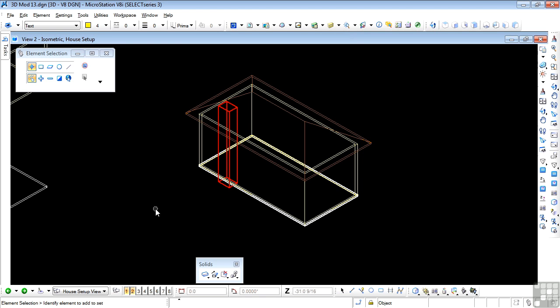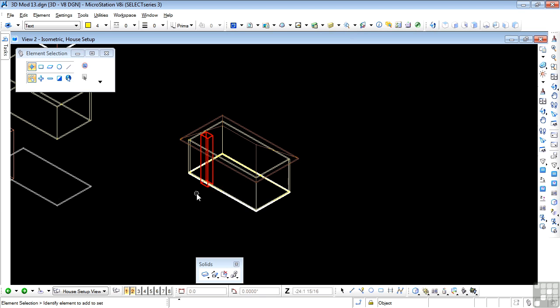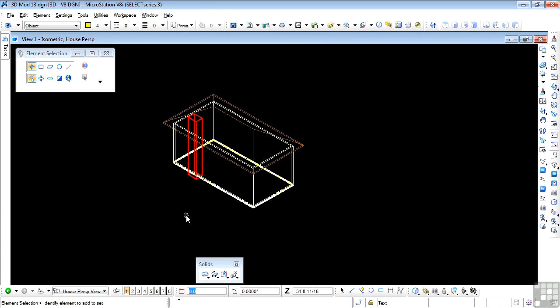Now that you have your house in place, we need to start looking at applying the camera. I'm going to change my model here to the same thing, but without the 4 individual items being displayed. Right now I'm in isometric. The camera is very simple to operate. Having selected the view to display the camera output, and having set the appropriate camera options, all that's needed are 2 data points. One is the camera location, and one is the target that the camera is looking at.